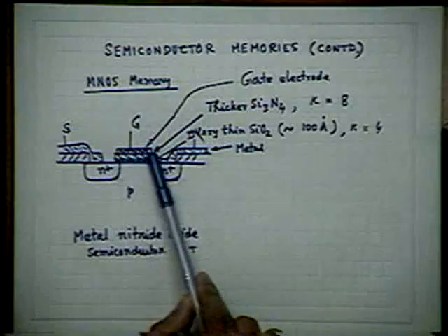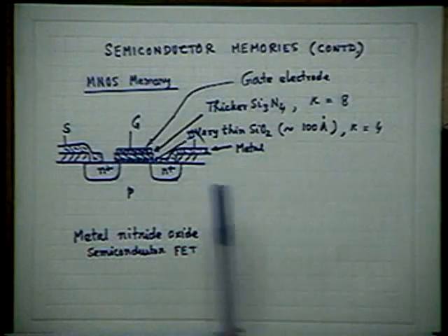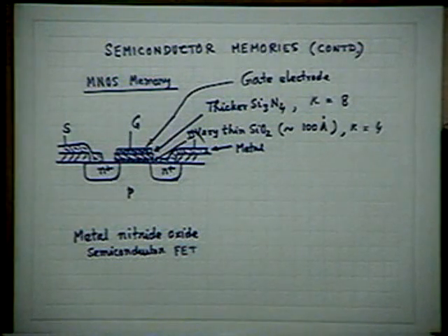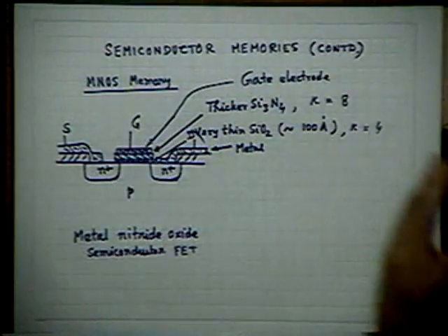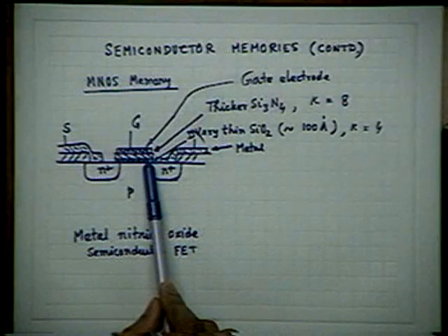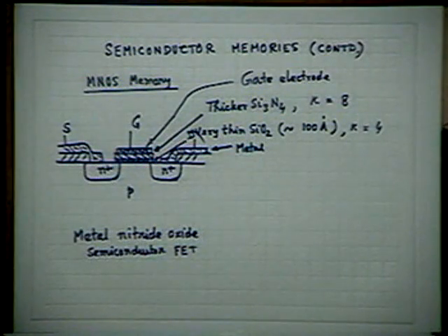Okay, and that will result in a negative charge layer located very close to the interface, and that will subsequently repel the electrons which were accumulated in the inversion layer, turning the device off, as discussed earlier. So what I have done here, I have been able to make the device off from on state by applying a voltage at the gate. But this voltage, please remember, is not the usual voltage. It is relatively high voltage.